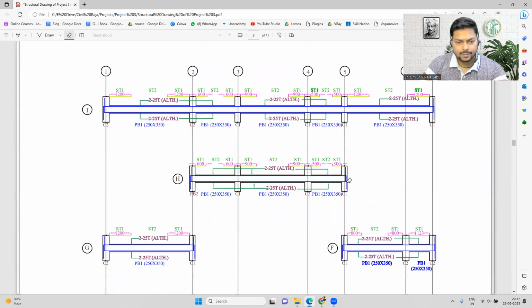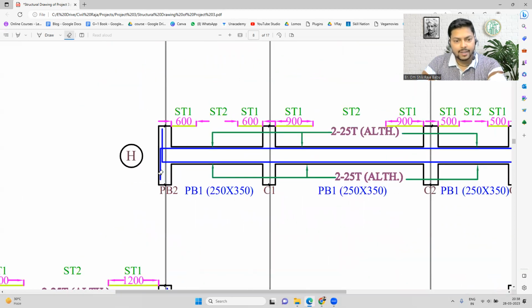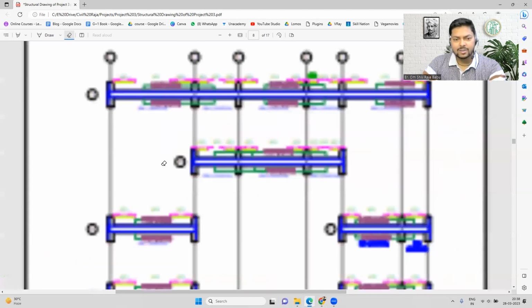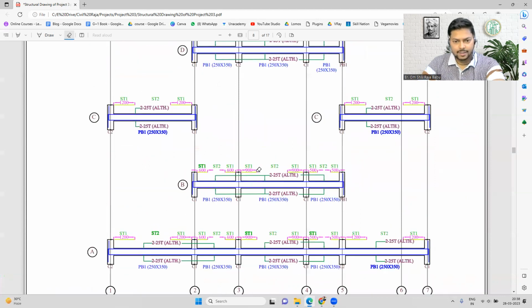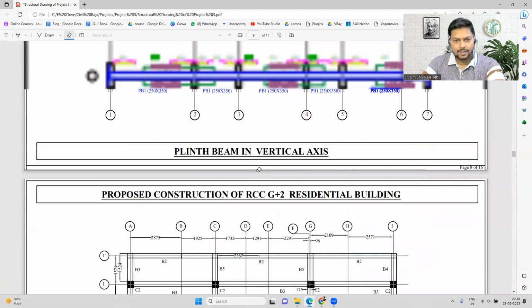Now let's go for the plinth beam. Wherever the beams are used as supports, if this depth is lesser than what is provided as the development length, then we can simply bend it like this. That is another case. Or for ease of construction, sometimes people also leave it till here. Both cases are correct. That is not an issue, because that will not affect much in such cases. So I guess there is no more extra point in the study of the plinth beams.